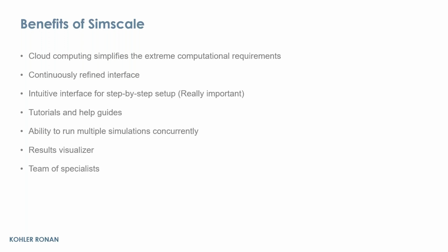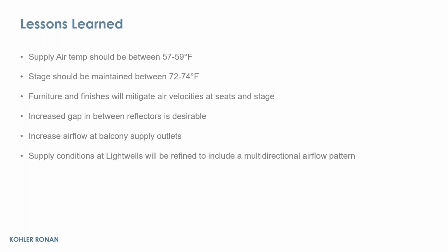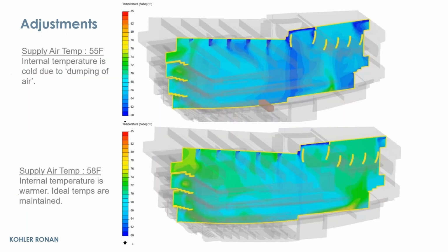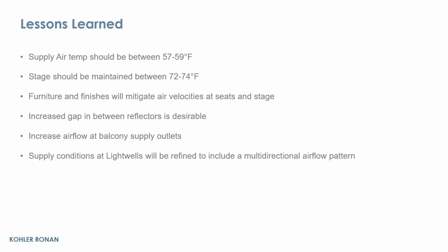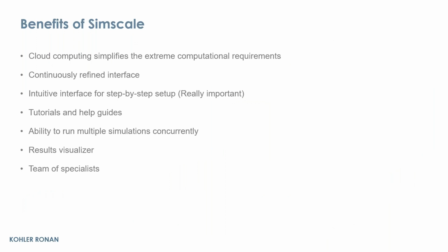which meant that you won't have any errors. We did find one really funny situation where my gravity vector was inverse, where instead of the air flowing down, my gravity was actually going upwards. So for the initial 2 or 3 runs, we just couldn't figure out what was going on. That was one of the funny things that happened. Why is the gravity reversed? And then we just figured out, oh, okay, it's just fixing the plus and minus sign on it.